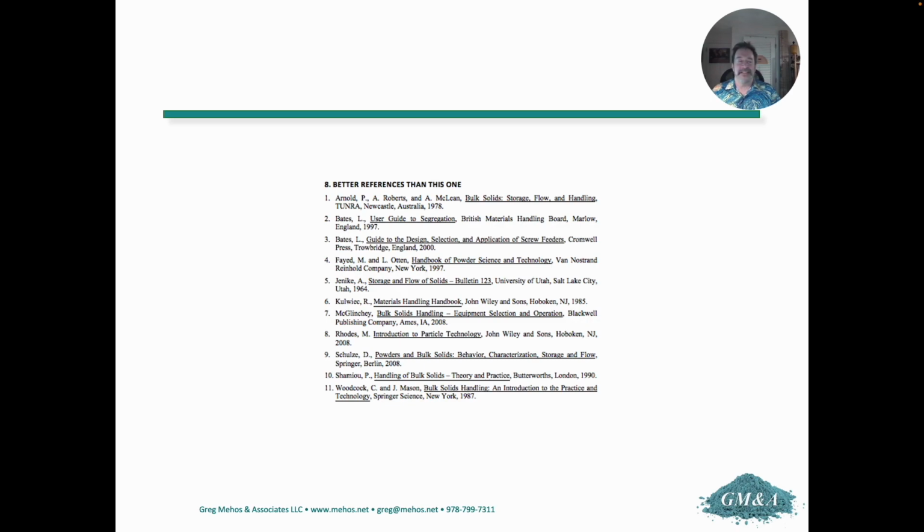You can almost see in my background my library. I have lots of good books. There's lots of good stuff out there. And it's a fascinating topic. And again, it's really, really easy, overly easy. If you think about it, if you want to make sure that material flows through the outlet of a hopper, just make sure it's big enough. If you want to make sure it flows along the walls, make sure that the walls are steep enough.